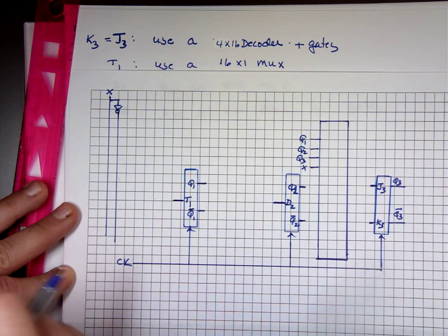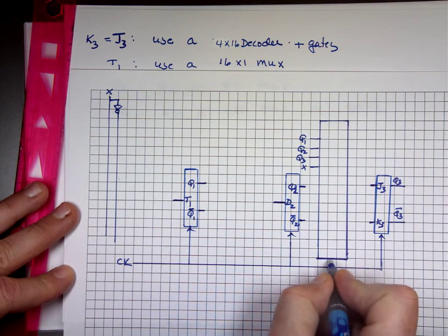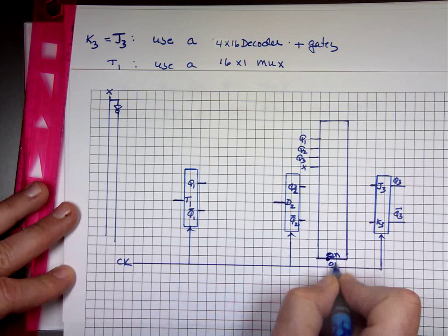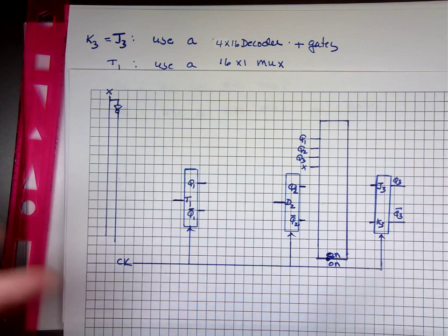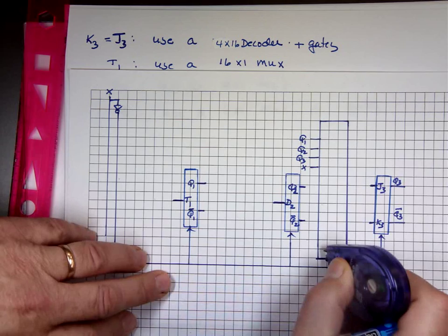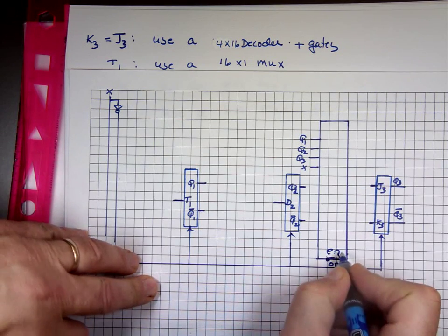Remember, the way this actually works, there's an enable here. I'm going to make sure that enable is on. I just go on, enable, and I want that to be on. Now, to be on, that means could be low, could be high. It depends on the chip we're using. That's EN for chip enable. It should have 16 outputs.